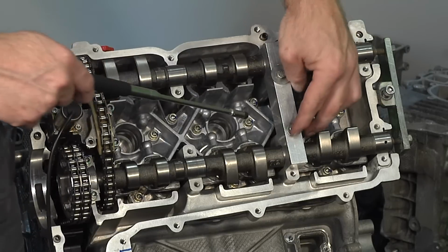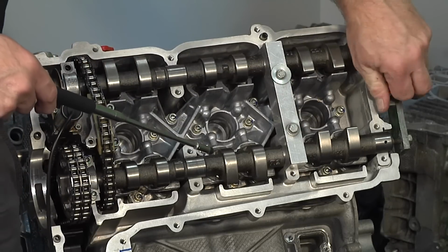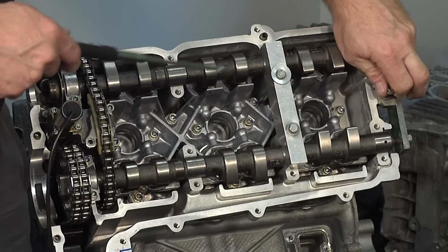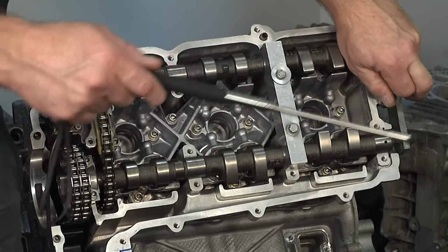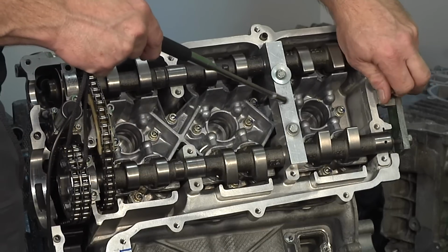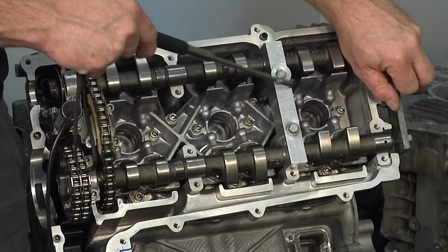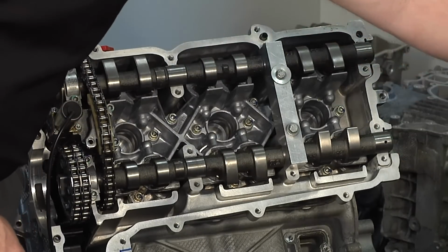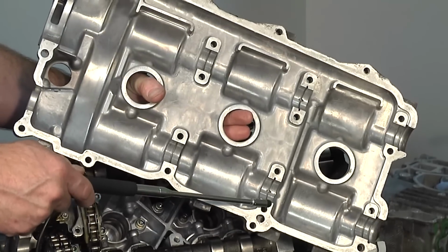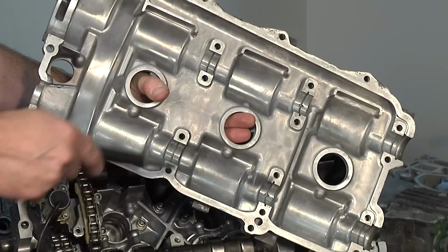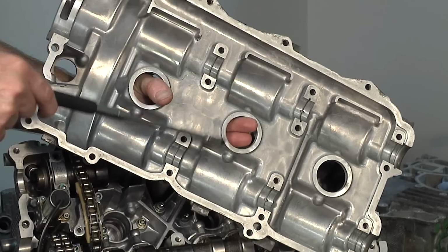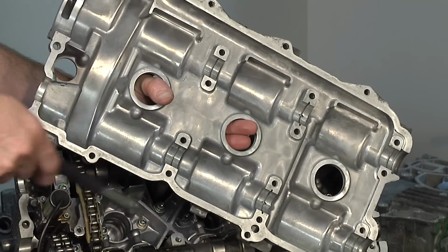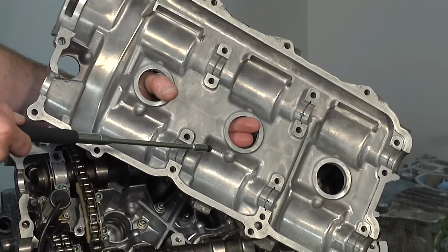So, with this bridge fitted, then we can remove the holding tool here from the rear. Now, this holding tool in the rear was only so we could pull the camshaft cover off to facilitate fitting the bridge here in the back. Now, what you have to understand is the camshaft cover actually holds some of the journal surfaces that hold the cams in. So the reason you have to do this is because once this is removed, there's nothing to hold the aft portion of this cam in place on either the intake or the exhaust. And then you have all sorts of things going on there that you don't want to deal with, okay?